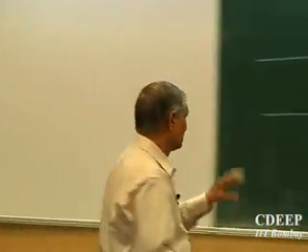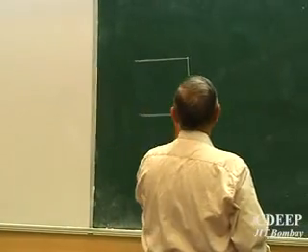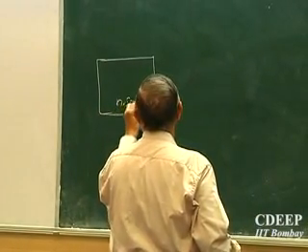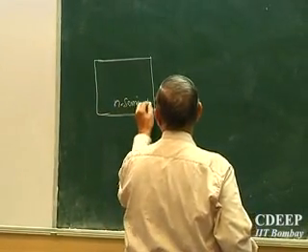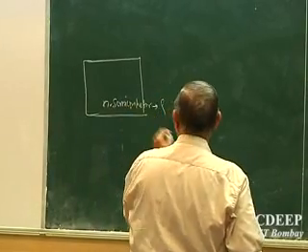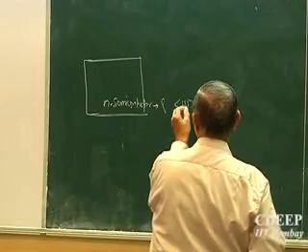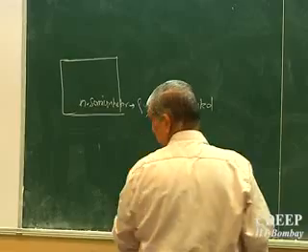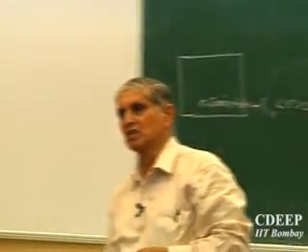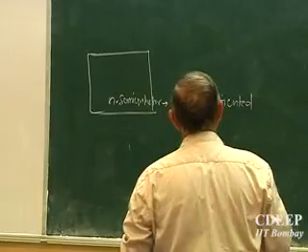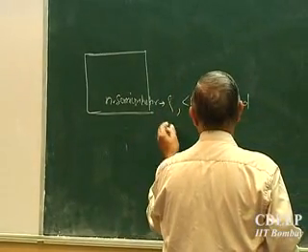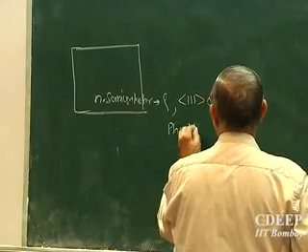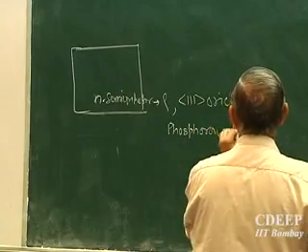But let's see, assuming something we know, something we don't know. Let's say I have a semiconductor. To start with, an n semiconductor, which has some resistivity rho, which is 111 oriented. This is given to you. Rho is maybe 2 to 4 ohm centimeter kind of thing, maybe anything right now. And if it is n-type, I would also say initially phosphorus doped or arsenic doped. All this data will be given.